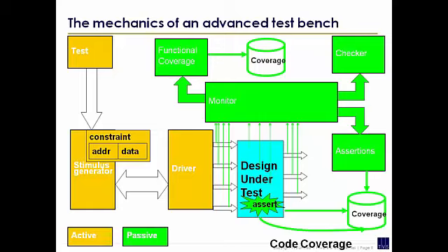Normally an assertion says, if this happens, then I expect this to happen, and it will give you what we call an antecedent and a consequence. So if A, then B. Okay, that's a typical structure of an assertion. If A happens, then I expect B to happen. And what assertion coverage does is to say, did A actually happen at any point in that simulation? Because if it doesn't happen, then your assertion passes vacuously. There is no trigger event, therefore this is a vacuous passing of your assertion. Assertion coverage would say, actually A never happened, so that assertion is useless. So assertion coverage is useful to say, did I actually have the trigger event on my assertion? Did my assertion fire? Okay, and you've got code coverage as well, and you've got functional coverage.